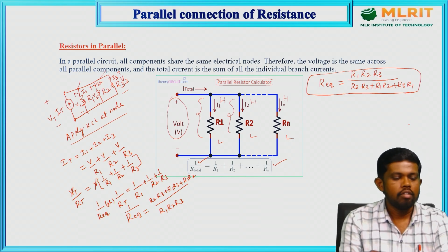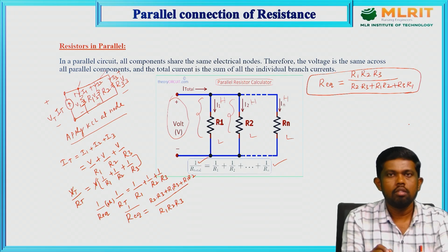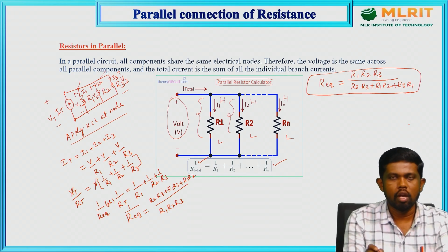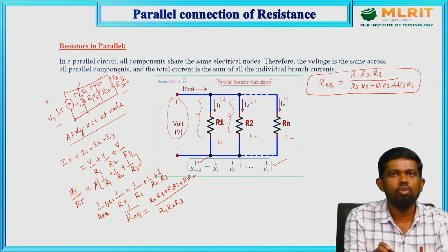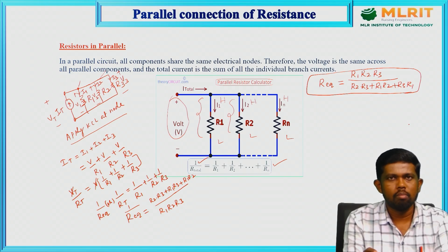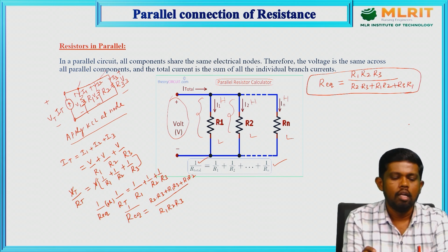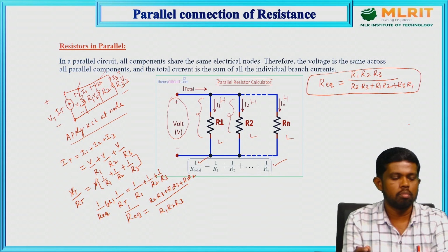So this is the parallel and series connection. In the parallel connection, there is no division of the voltage, only the current is divided into I1, I2, I3, and so on up to In. In the series connection, there is no division of the current. Whatever current is given by the source is maintained by the same amount in every element, but the voltage must be divided in the series circuit, because there is a potential drop across each and every element. So in series the current is constant, while in parallel, the opposite: the current is divided and the voltage is constant.